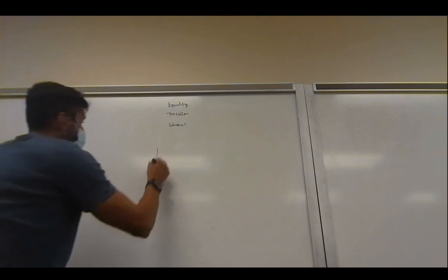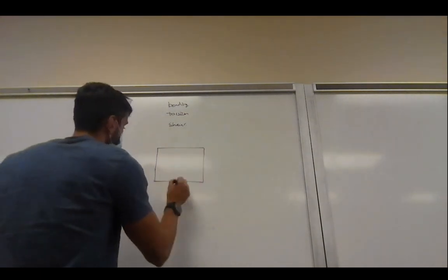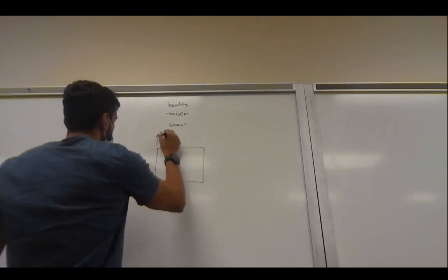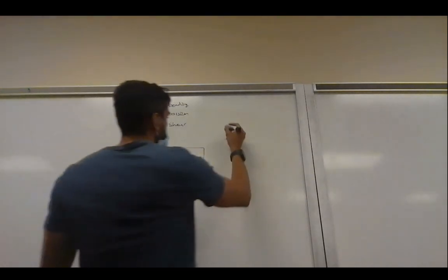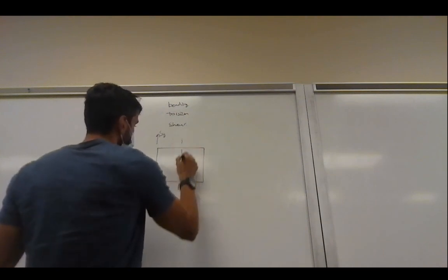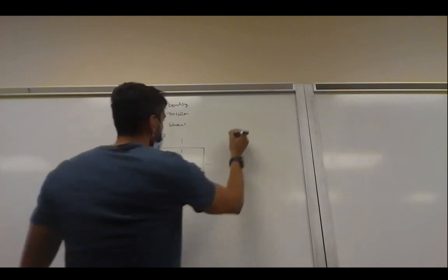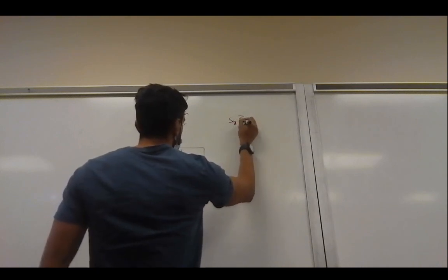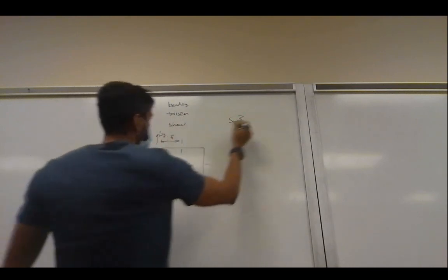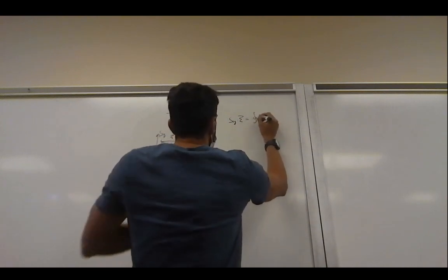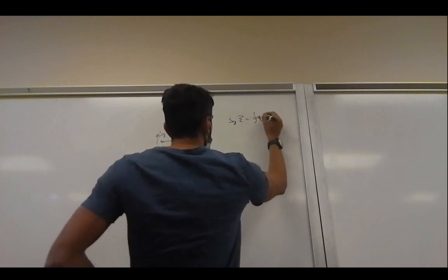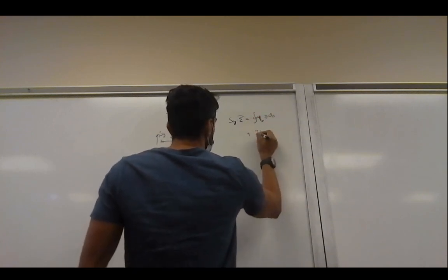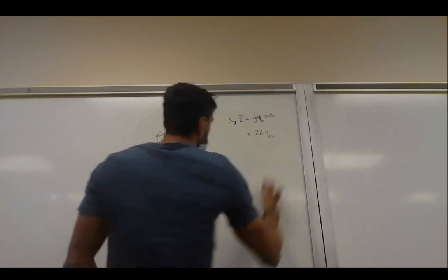Say, for example, we have something like this, a wing box, and we know that the shear force is acting here, right? One way to solve this, as I mentioned earlier, is to take the moment equivalence equation around this point in the center, and I said, well, you have Sy times ξ, this being ξ, is equal to the integral of qb ds plus 2 times the enclosed area times qs0, right?